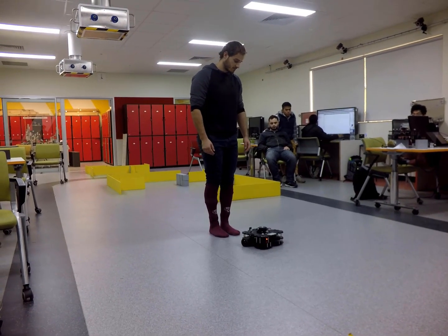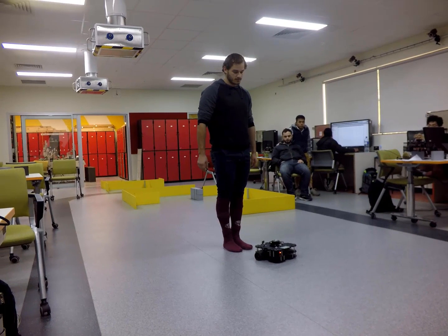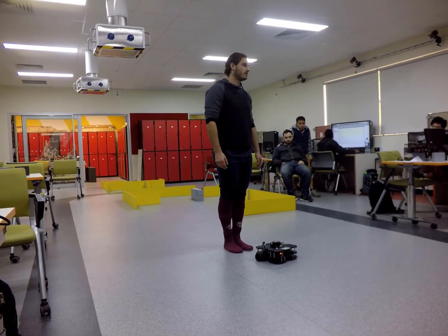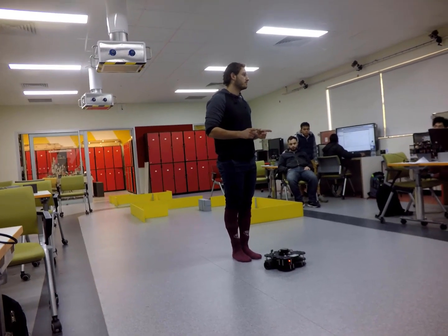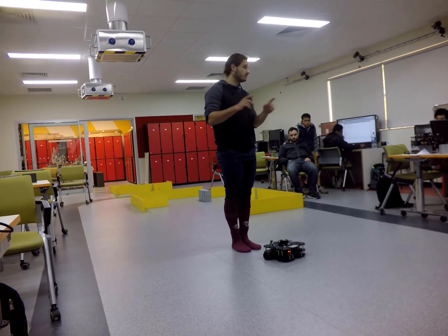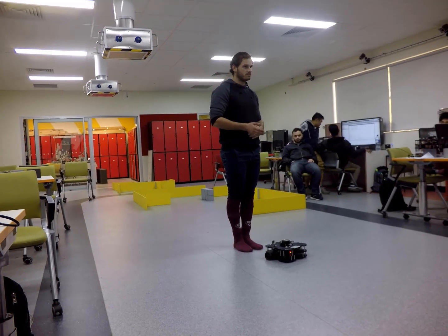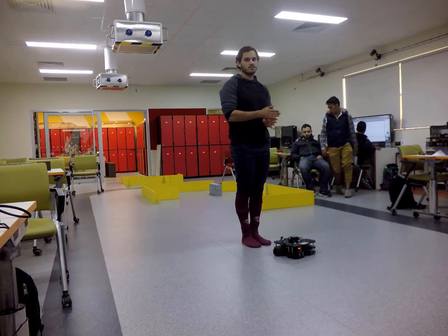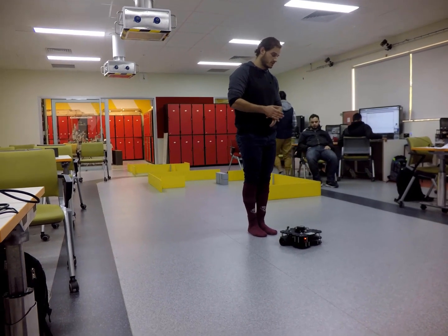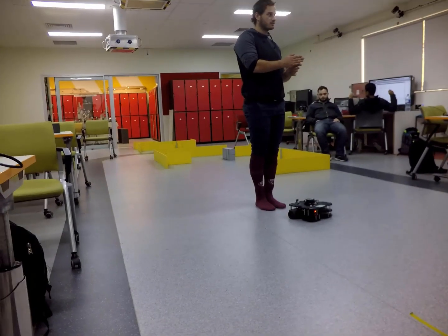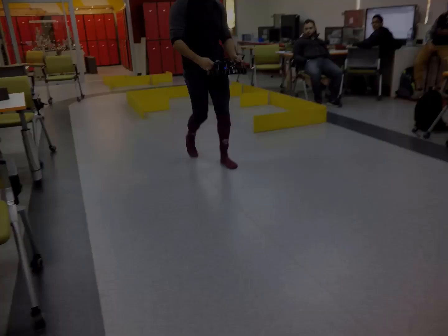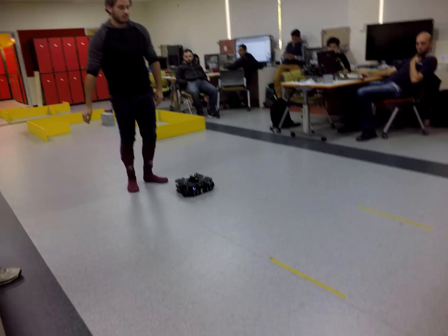And so yeah, back to the bounding box. It'll take the start and end location of the X position of that bounding box in the total field of view of the camera, add them together, divide by 2, and you get the midpoint of that bounding box. If it's less than 200, it'll turn to the left, and greater than 200, turn to the right.